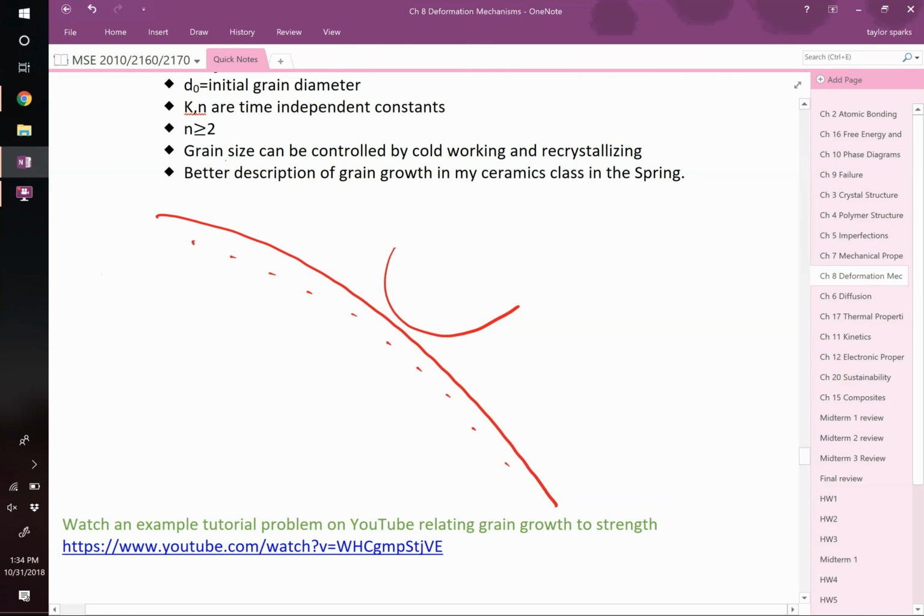Yeah, so if this is a grain boundary that is a very large grain, that grain boundary has what we call a very large radius of curvature, compare that with this one, right? These atoms with the small radius of curvature from a small grain are locally more strained along that grain boundary than these ones are. So these guys over here are just less happy than the ones over here. So if they have the option to dissolve, if they can leave that grain boundary, this atom gets up and travels over here and then redeposits over there on the surface of this thing, it will do so.